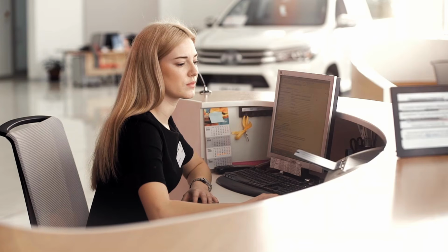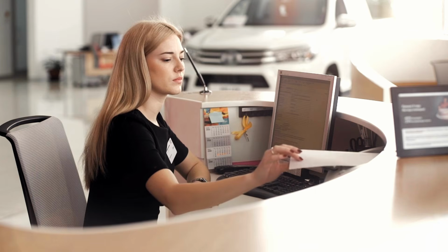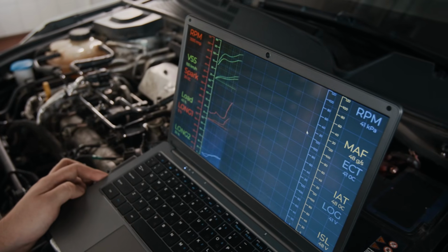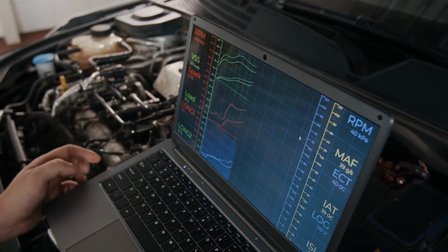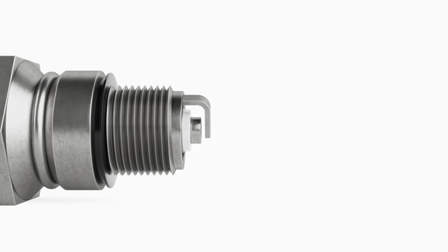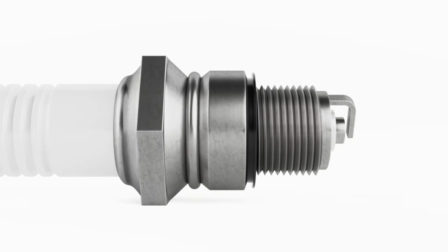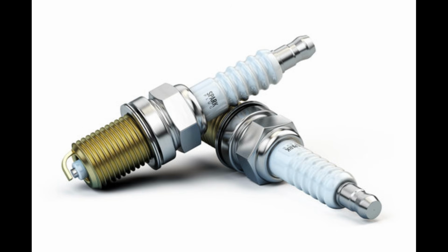Here is the polarizing truth about this situation. The automotive service industry is not incentivized to tell you about a $5 fix. A mechanic who identifies a rough idle, reduced fuel economy and slightly sluggish throttle response will naturally reach for the high-value service items first. Spark plugs, fuel injector cleaning, throttle body service, oxygen sensor replacement. All of these are legitimate maintenance items. But if the root cause is a fouled MAF sensor that costs less than a sandwich to replace, the expensive service items will restore performance only partially because the fundamental data error feeding the ECU has not been addressed.